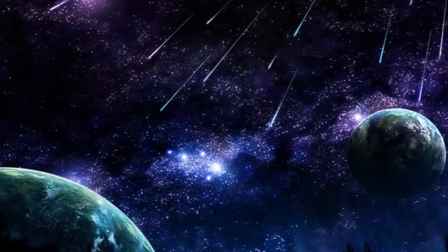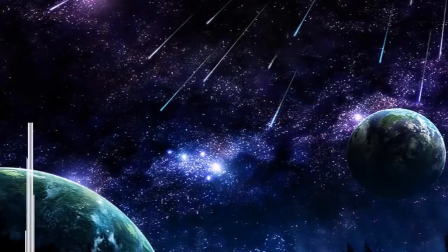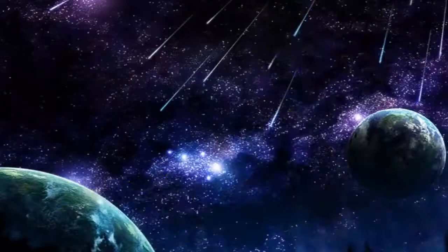The compressor is equipped with an automatic suction shut-in valve on each inlet and a discharge shut-in valve. Many operators prefer, and in some cases regulations regarding compression require, automatic blowdown valves, and all of these are subsequently installed to ensure that we achieve this.